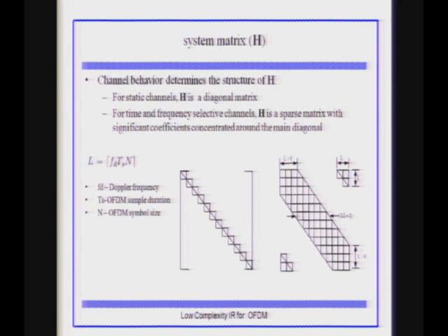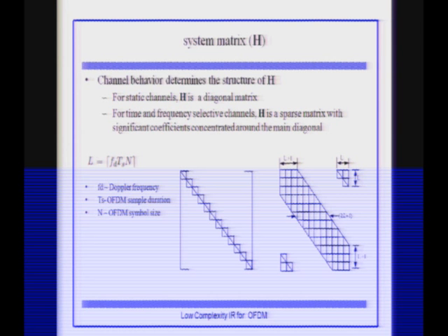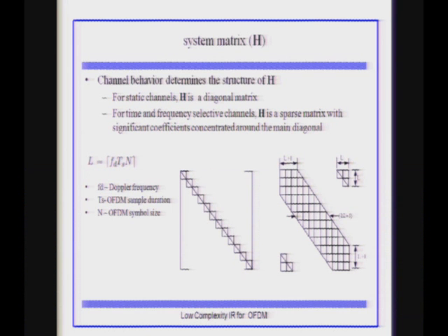But in the current existing scenarios, generally N is 256. Now if we talk about the 802.11 series, we are talking about N being equal to 256 or 128 or 64. And so in these cases, what is available today, they generally ignore those off-diagonal coefficients and off-diagonal elements and keep going as if it is a single tap equalizer.